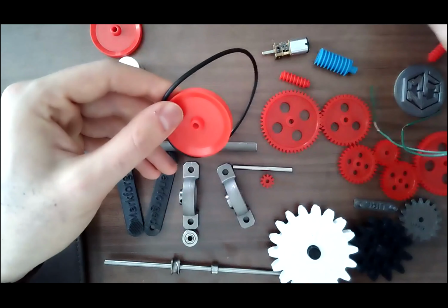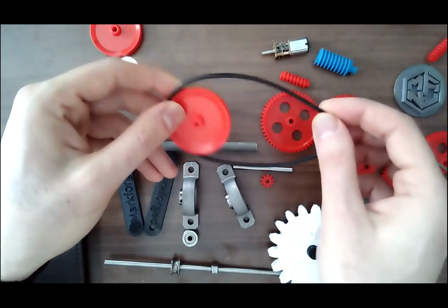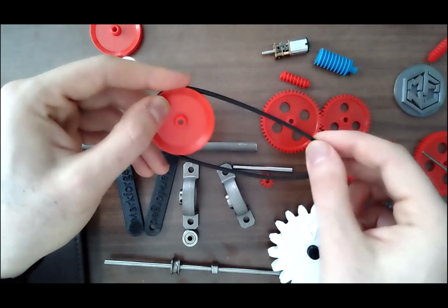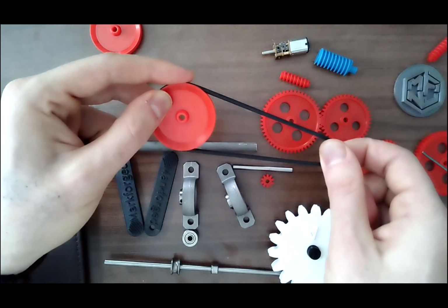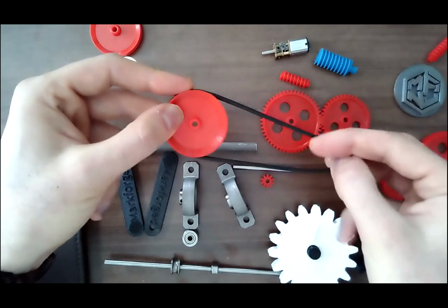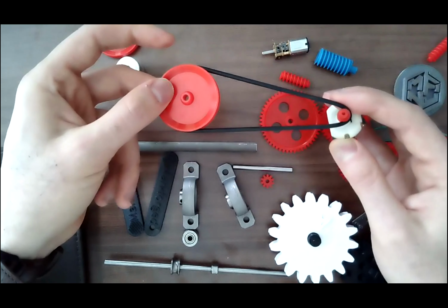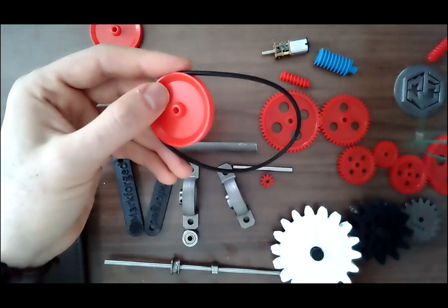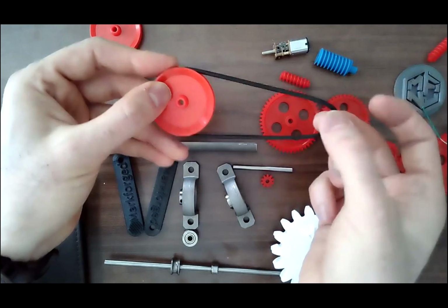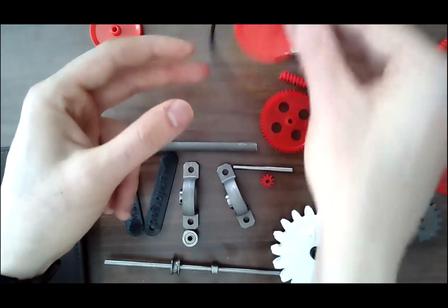So belts and pulleys are good. However, they require maintenance, the tension for the belt, and they get loose. Also, they wear out very fast. Besides, they require a lot of space. So you can imagine from a motor from this point, getting there, I need a length this big. So another solution is to use gears. Instead of transferring power from small to large pulleys, now we'll switch them with gears.